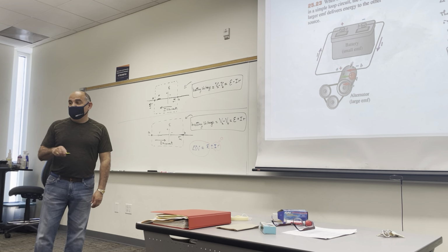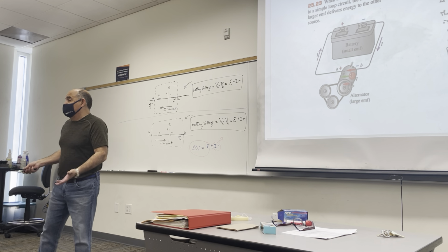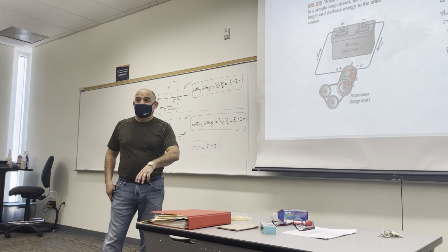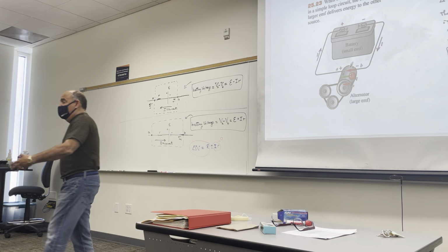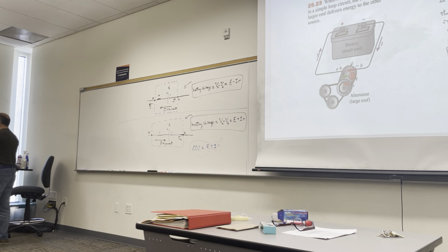But it could be that the alternator is the one that's bad, and that your battery, well, it's dead because it wasn't charged by the alternator because the alternator wasn't working. Right? And then instead, what you need to do is buy the alternator and not a new battery. With the new alternator that works, then it will charge your battery that's still working, instead of having to buy both of them. Right? So, just so you know.